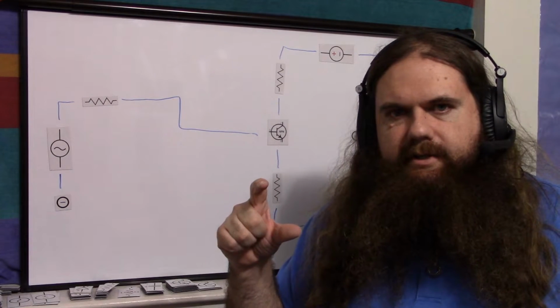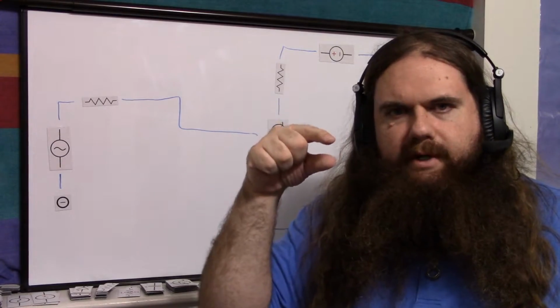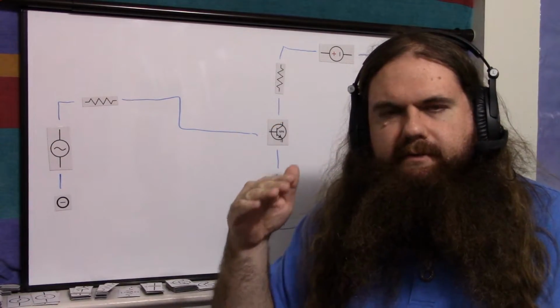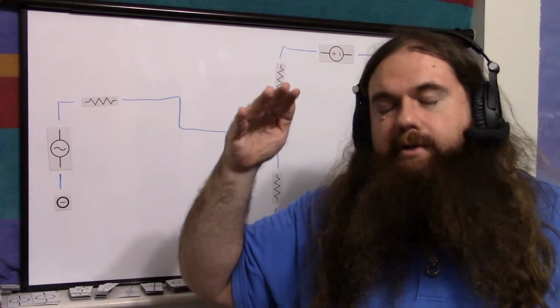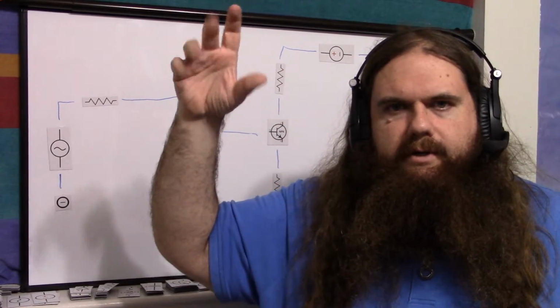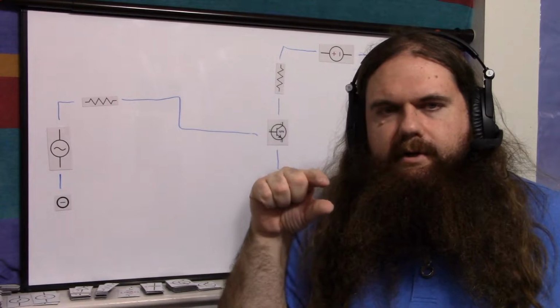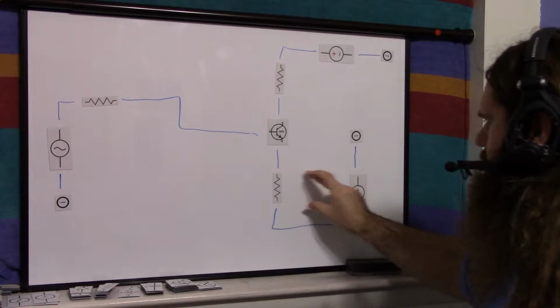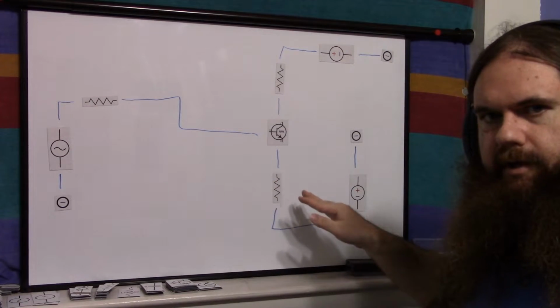Your emitter resistor was configured for 1 volt at quiescence, so you add 1.7 volts, so you bias it to 1.7 volts, and you've got 1 volt of wiggle room. 0.5 down, 0.5 up. Actually, yeah, 1 volt down and then more up, because it's however much your supply voltage is. But you can go up to a volt down before you risk turning off the transistor.